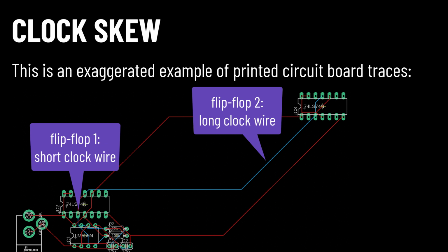While this difference is largely trivial in the types of circuits we build in class, it may impact a circuit if there's a big difference in path length from one flip-flop clock input to another. Clock skew is not uniformly a bad thing, but is a consideration that must be made when designing a circuit.